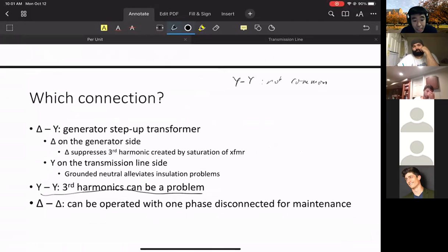So when you're taught about transformers, what we said is if it's balanced three phase, then you don't need a common ground or a return wire. But often in practice, you're not exactly in balance. It's hard to say these three phases are exactly in balance, that the angles are exactly 120 degrees apart,